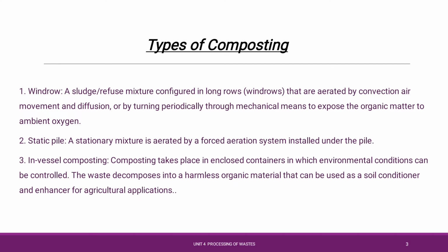The continuous turning may help in the proper provision of air supply within the waste products, thereby promoting rapid oxygen transfer. So the duration for the organic matter degradation to form compost is only about 1 week, or it may take up to 4 weeks.